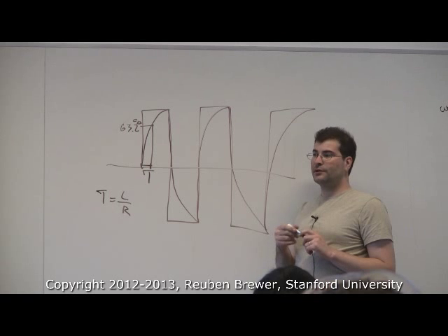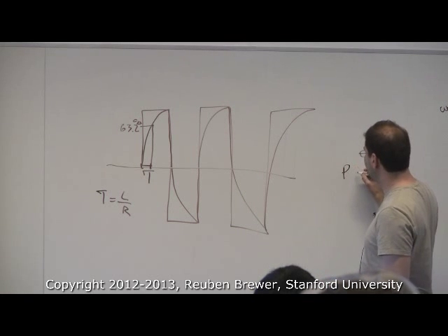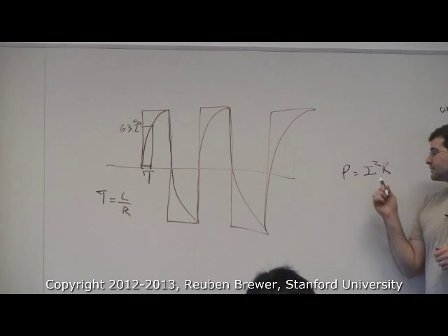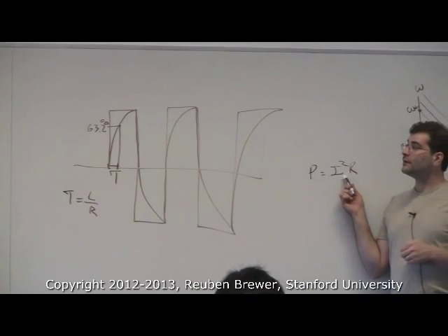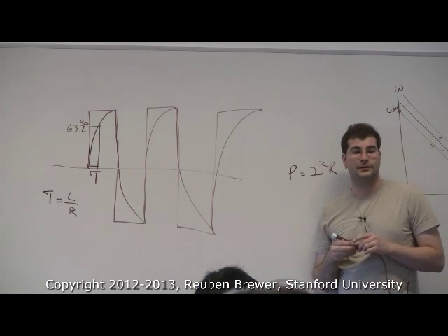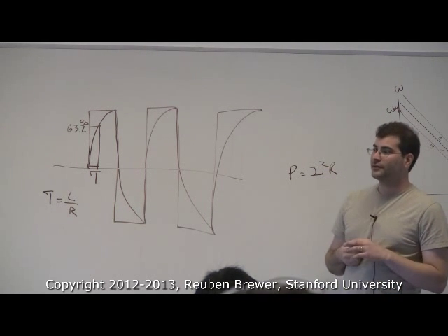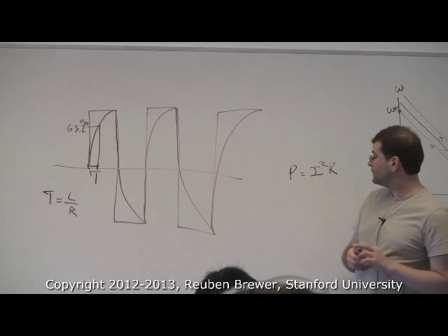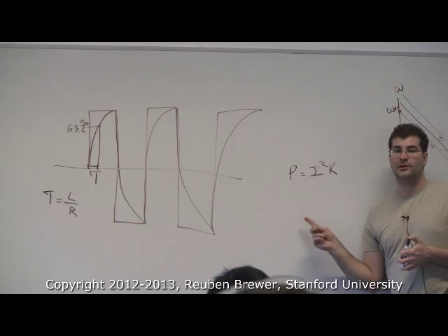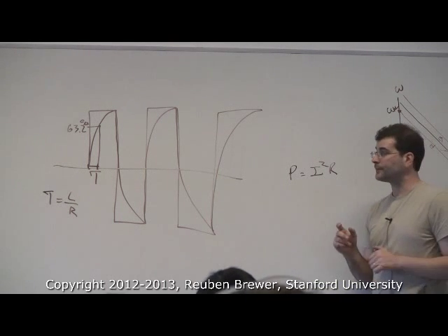Now everyone knows that the heating power loss from a resistor is I squared R, right? And from our electrical model over there, we have a giant resistor in the coils. So any current that isn't what we wanted is getting dissipated as heat, heating up our motor, and eventually our motor's going to quit working.